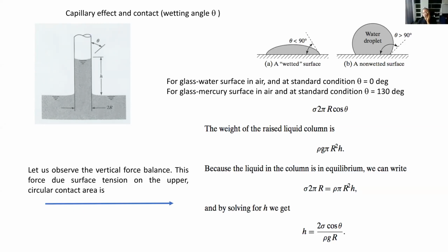So now we can do the same example. Let's pick up a case when the fluid is wetting, like coffee or something. The angle is less than 90, therefore the fluid will climb up on the sides of that little tube. Let's say this is some kind of glass tube. How much is the force pulling up the liquid? It's going to be equal to the peripheral circle, which is 2 pi r, but not the full 2 pi r, it's cosine theta, because it's not acting straight up, and then times sigma. So very simple. That's the force pulling it up.